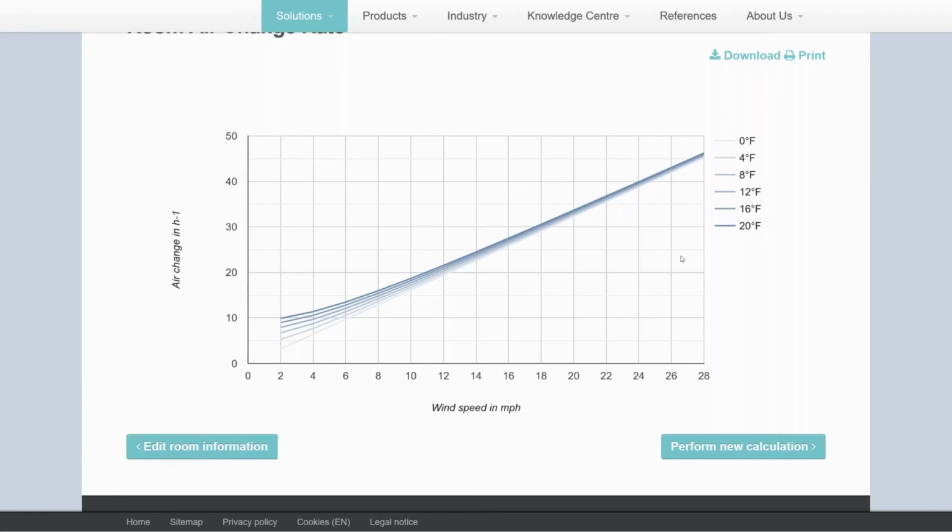Yeah, and then we have another question, in relation both to control, but also in relation to the result. If you look at the result graph of the calculation, of course, when you have rising wind speeds, you will get a very large air change rate. So of course the operable windows should adjust based on this, based on input from the weather station.